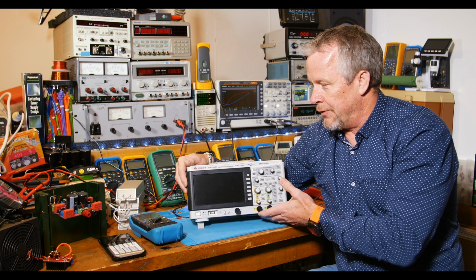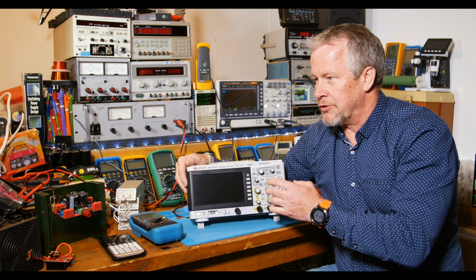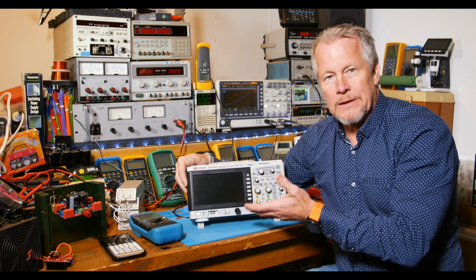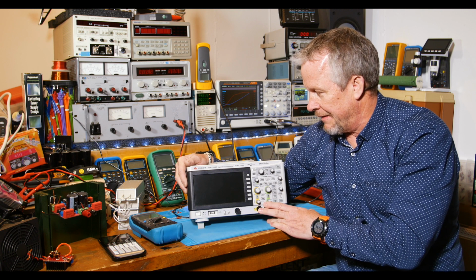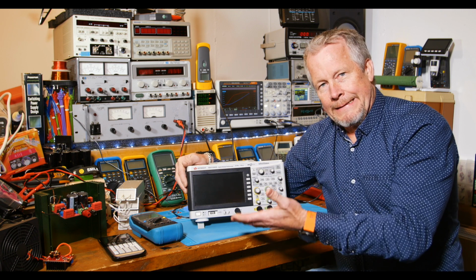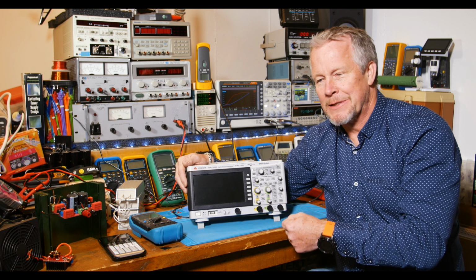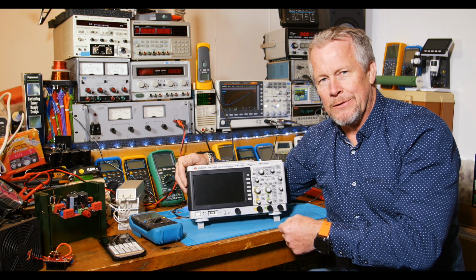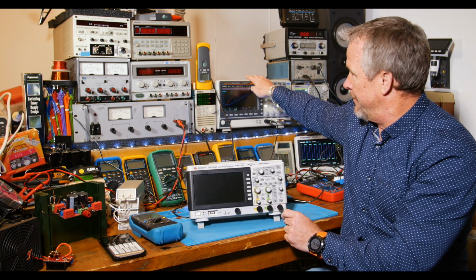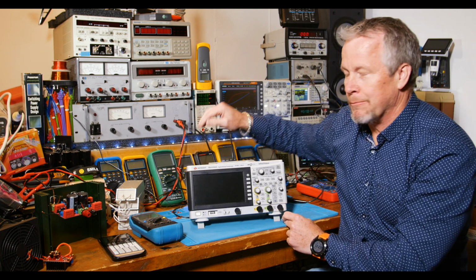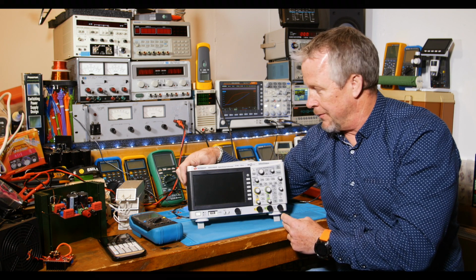So you can do that for your inductors, your capacitors, your resistors, individual components like that, as well as doing the full-blown filter, input impedance, output impedance, that kind of thing. So I really like the FRA stuff. If you are comparing 2 scopes, and one has the ability to do an FRA, then you may have seen some videos I've done where I've used this scope to do this kind of analysis, and I think it's very useful.